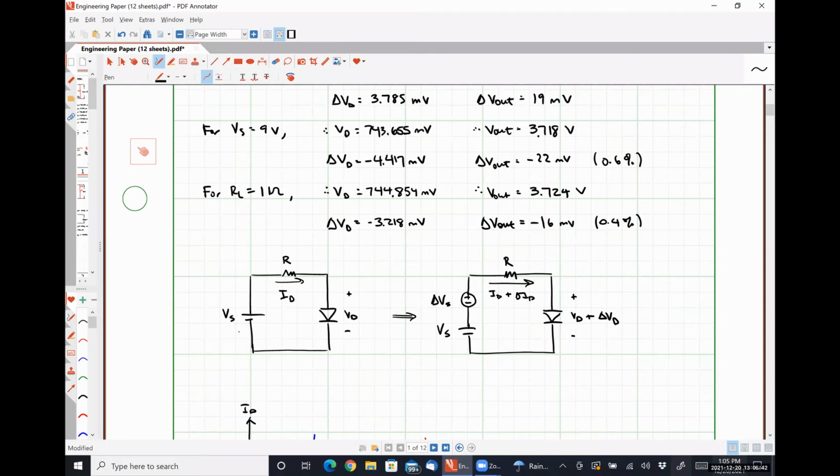This dynamic resistance approximation is valid if the change in VD is around 5 millivolts or less. So if the change in a single VD is 5 millivolts or less, this is a good approximation. Anything beyond that, and it starts to get a little bit questionable, because the shape of our exponential may have changed significantly in that swing.